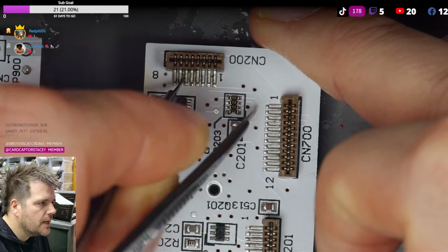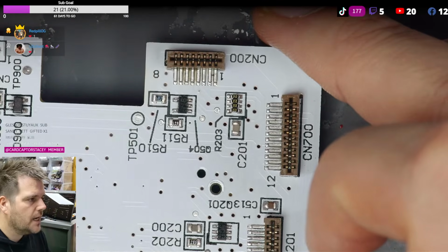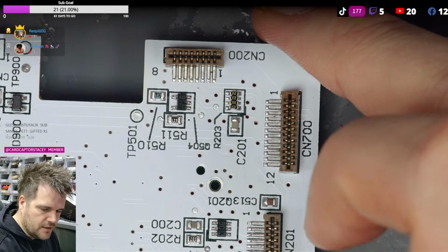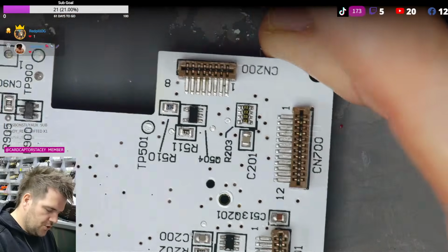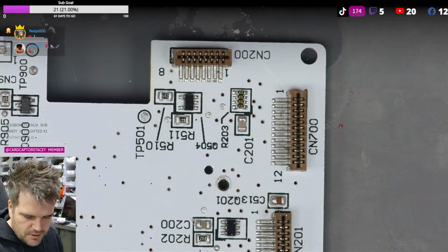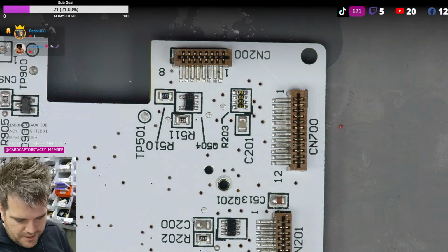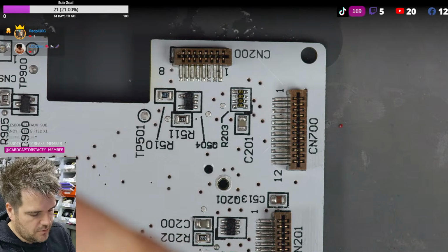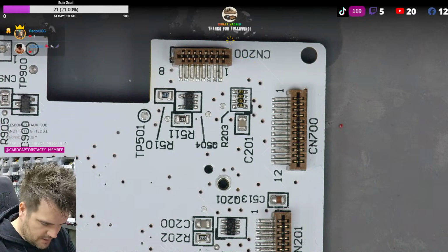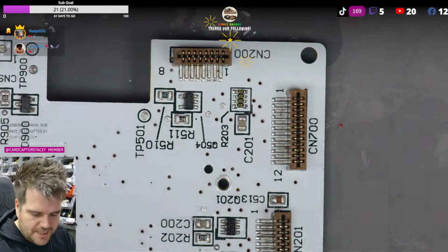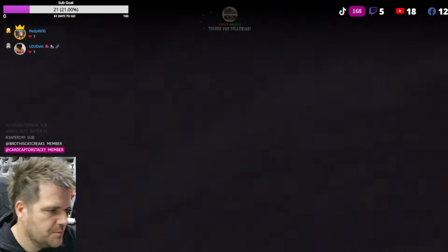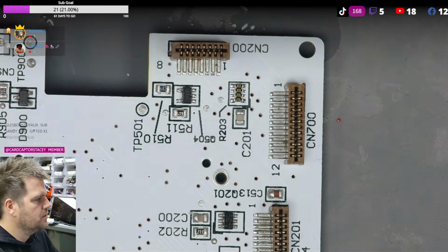But yeah, if you can hot air, like I do, I'd highly recommend the hot air over other things. It's just with plastic as well, you also have to be careful that you don't melt things. So there's a balancing act between ease of solder and also the risk of doing damage to a board. You have to balance the techniques you're using, and it changes per board as well. Everything's different per board.